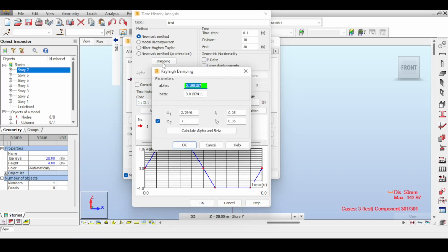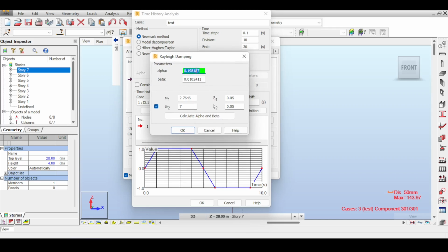Now this is extremely important: you need to understand and read about modal damping and, of course, the shortcomings of damping, because the entire damping thing is kind of strange. To try to intrigue you, we assume that structures dampen by assuming that the model for damping is a viscous damper. Meaning, for example, if you take a stick and move it in water, your movement is resisted, and the faster you move, the more resistance you face. This is somehow similar to our assumption for damping.